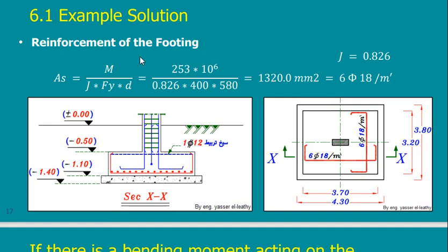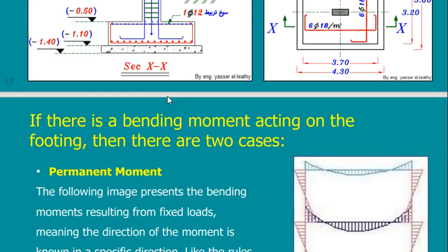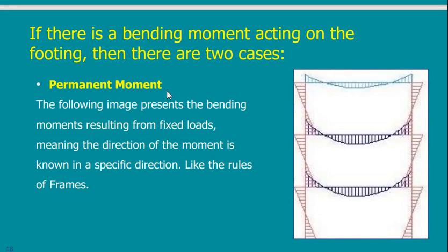So isolated footing means that it is carrying vertical load. But footings carry more than vertical load. It may carry moment, it may carry horizontal load. So I have to check other cases. The important case that I'm going to design is the moment.